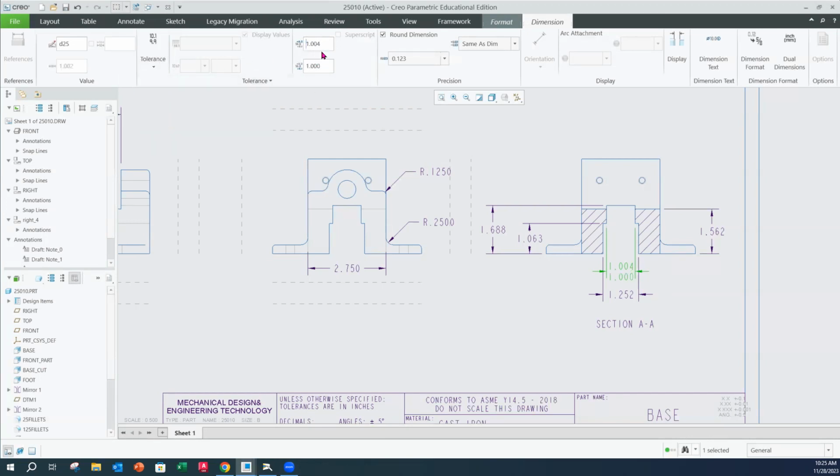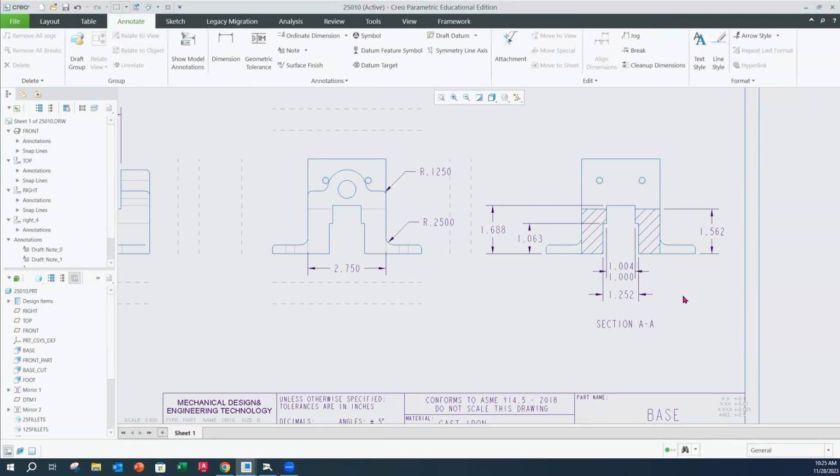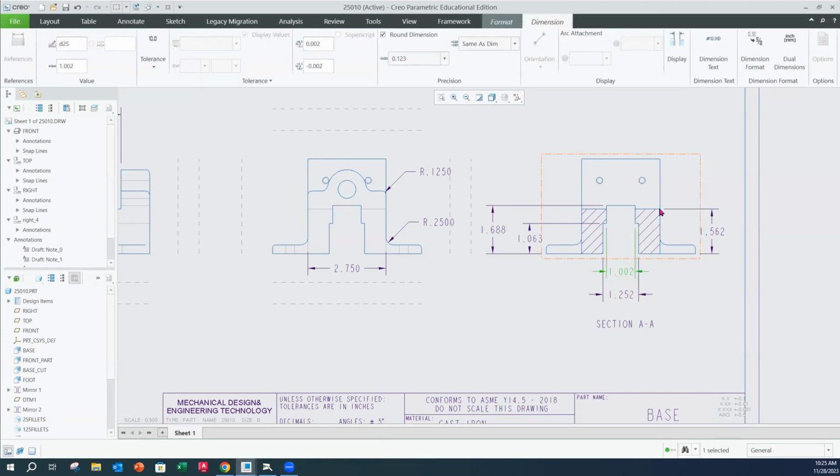And now you're going to notice that it's showing it as the limits here, okay? And it's showing it down here as the limits as well, okay? So you have to set up the tolerance first before the limits are going to show. So if I go back to, for instance, if it comes in as my nominal value, and I'm going to click on that dimension again, and let's say there's nothing listed here, nothing listed here. Is it going to let me do that? Zeros, whatever the default would normally be, zeros. Okay, so there's nothing in there, all right? And if I try to go over here and say, okay, I want to set my limits, of course it's going to remember it because it's so smart, but you may have problems doing that.